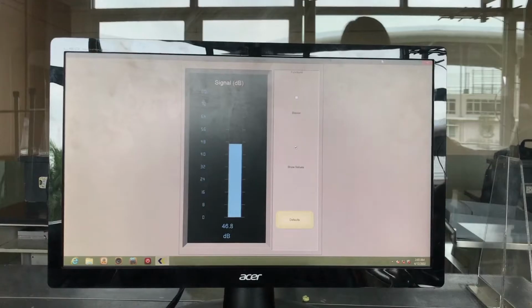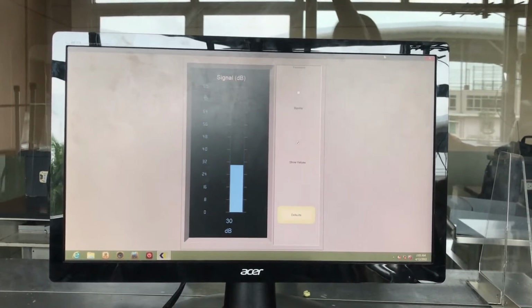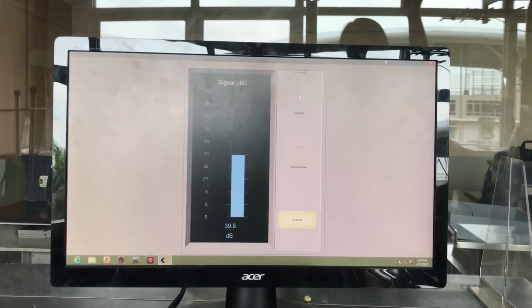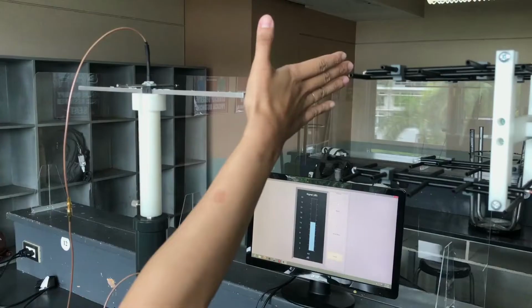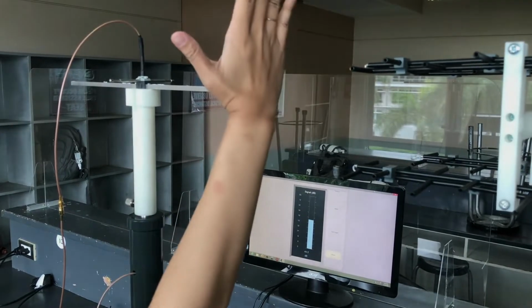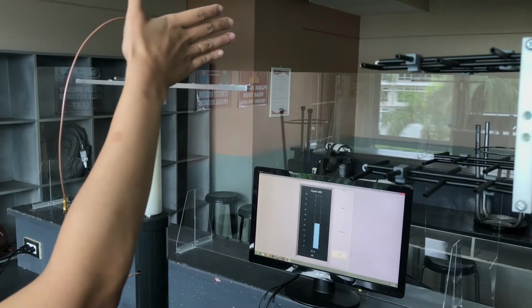In addition, the hand that was placed as close as possible to the transmitting antenna revealed a reduction of approximately 38% in the RSL. Based on the data, the appearance of an obstruction directly in the path of the transmitting and receiving antenna directly affects the received signal level.